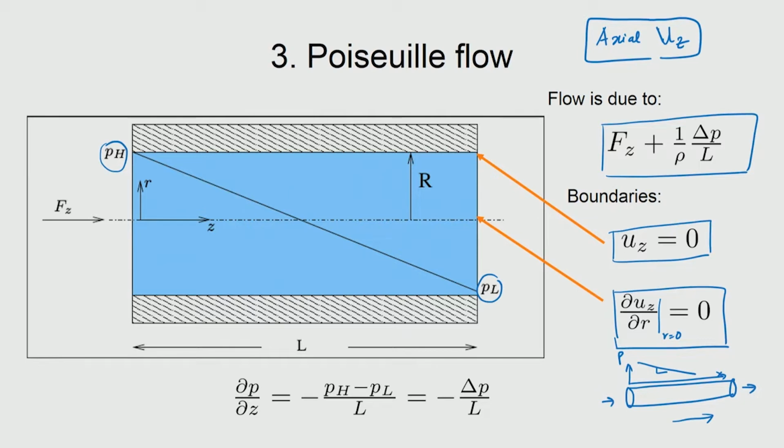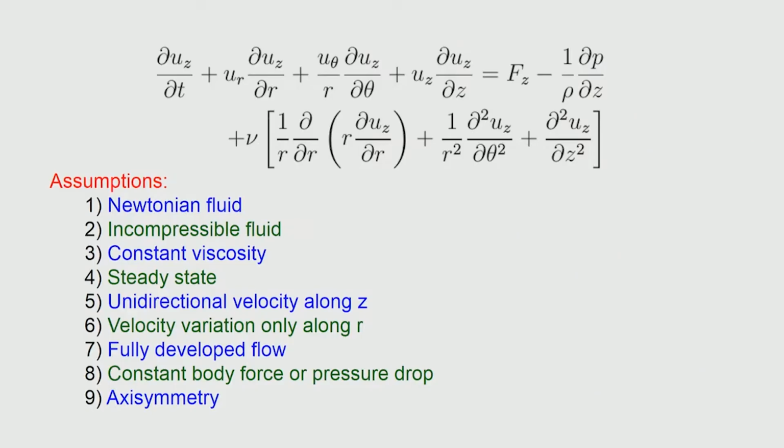So, what is the equation that we need to write for this particular problem? We have the Navier-Stokes equation for the z component of the velocity. That is what we are going to write. We have already written the equation, which means that we have already made these three assumptions, and more than that we are also going to make further assumptions.